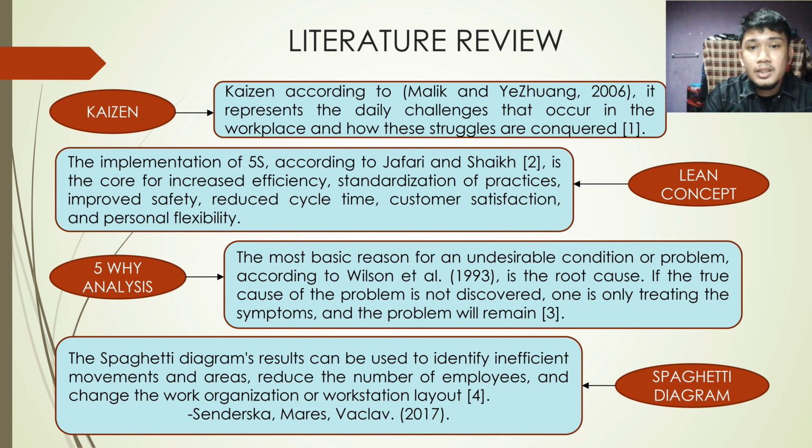These are some literature reviews for the project. Kaizen, according to Malik and Yuzan, represents the daily challenges that occur in the workplace and how the struggles are conquered. While for the lean concept, the implementation of 5S is the core for increased efficiency, standardization of practice, improved safety, reduced cycle time, customer satisfaction, and personal flexibility.